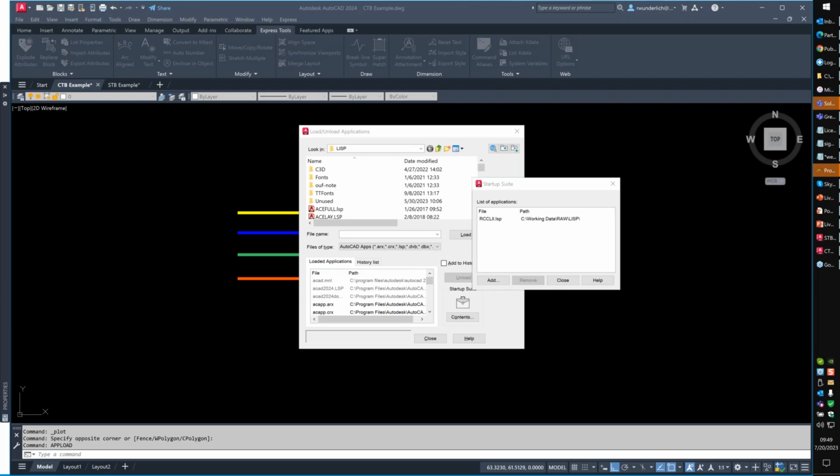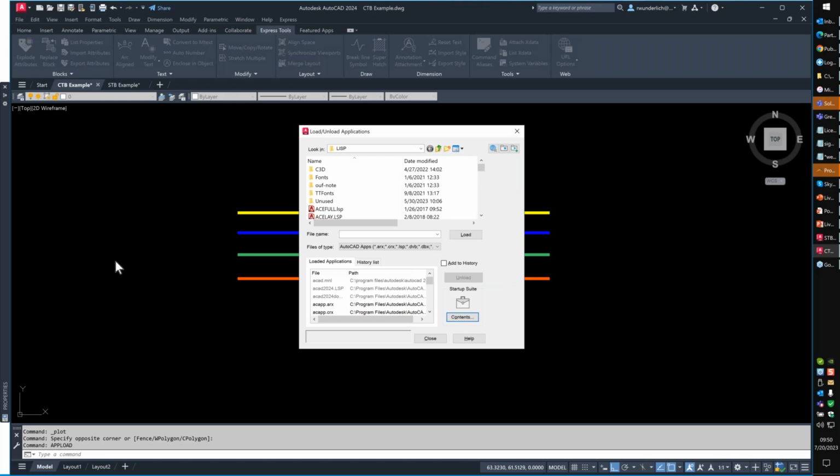All right. Do you recommend a PCL driver over a PostScript or an HPGL2 driver? I generally find that the PCL drivers, especially PCL 6, work very well for the AutoCAD-based products. Some of the older drivers are still on PCL 3 or 4. The HPGL driver does work in a lot of cases, but as soon as you add an image, like a JPEG or a PDF underlay, it tends to cause that engine to crash with an overrun. So just be aware, there are some updates that help correct that, but in some cases you have to go with a PCL driver or you have to plot to PDF and use that.